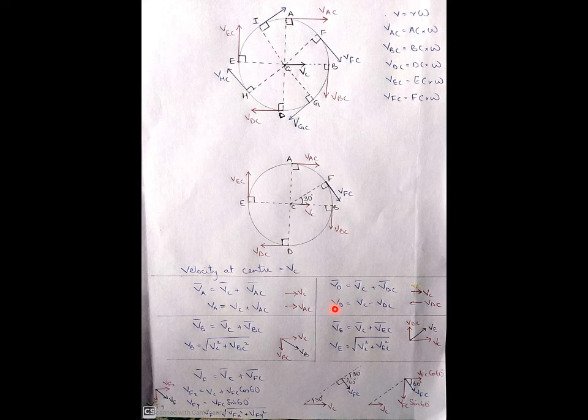Now in the next step, we will be calculating it originally, which means velocity at the point D equals... Now avoid the vector addition. See in which direction it is moving. Velocity VC is towards right, while velocity of DC is towards left. So if you are avoiding the vector addition, then velocity of D point will be VC minus velocity of D with respect to C.